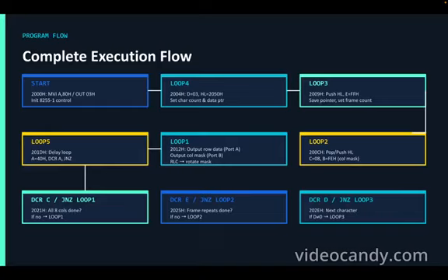So here the loop, which is loop 4, and here D is equal to 03, which tells that there are a total of 3 characters which are going to be displayed, and this HL value is 2050, which is telling where exactly the data of the individual characters that I want to display is stored.